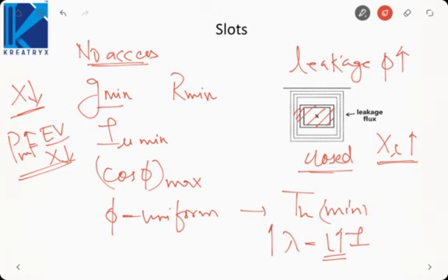And here also, as in case of synchronous machine, we will use distributed and short pitched winding on the stator side. So the stator construction essentially remains the same, just the nature of stator slots changes. In case of synchronous, we use open type of slots. Here we use semi-open type of slot. Closed slots are never used because then we will never be able to access the coil.